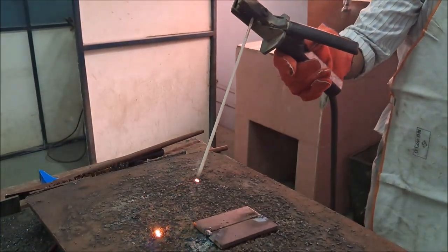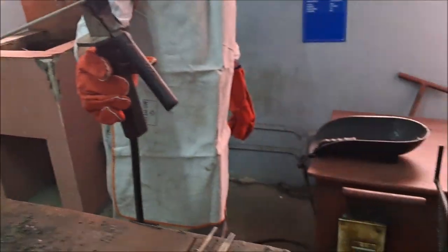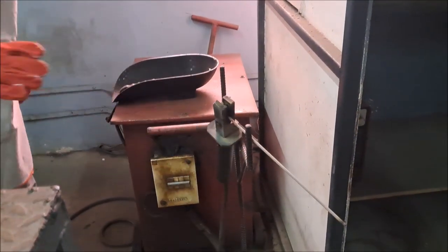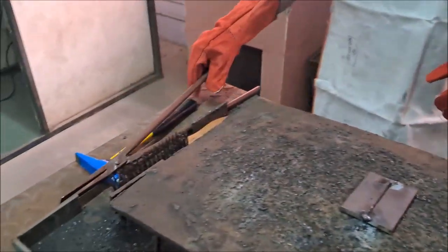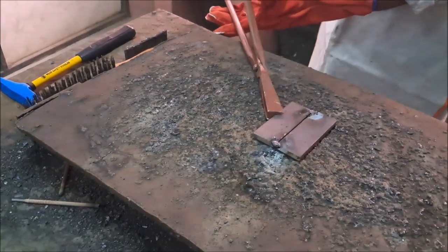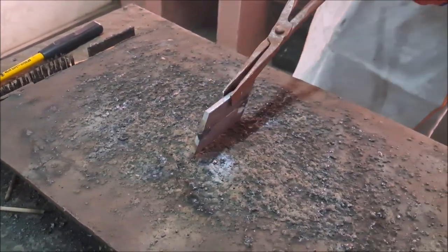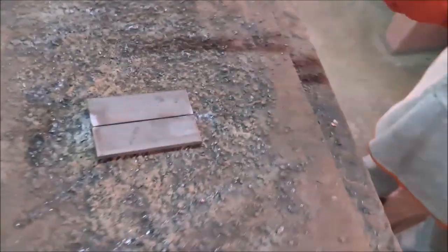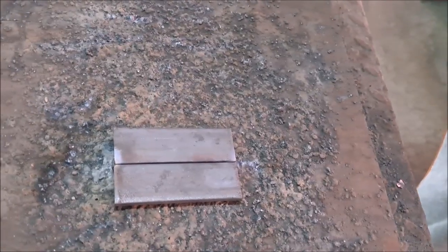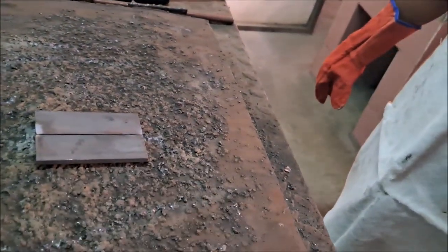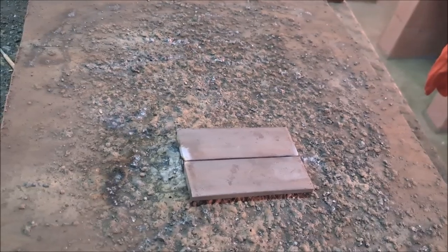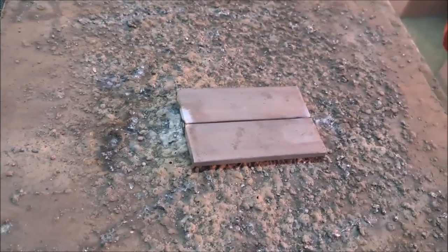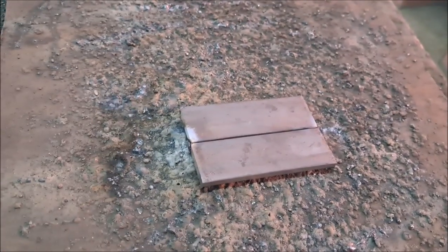After tag welding, hold the electrode holder on the stand like this way. Don't handle it by hand. First complete the tag welding and keep it on the stand. After that, using the tongs, take the workpiece and flip it. This is the right way. Don't touch it with your hand, because your plate will be heated to a high temperature, and suddenly your hand will be damaged. So using the tongs, you can easily flip the plate to the other side.